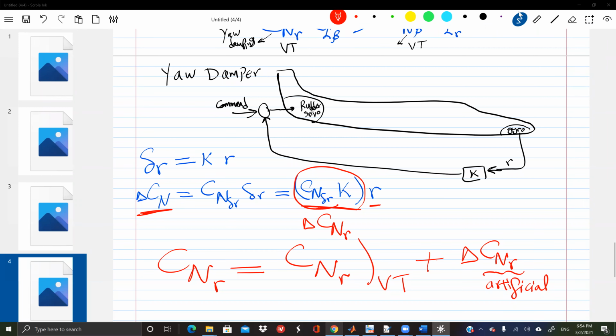So far, so good. Could I ask, are you basically just increasing the rudder angle a little bit with your gain constant? This will be continuously happening during flight, and the rudder angle will depend on R. There is a rudder angle for trim if needed, though usually there is none. There is a rudder angle coming from the pilot command. I'm not talking about that. I'm talking about the additional rudder angle for feedback control. This is proportional to R, the yaw rate of the airplane. So if the airplane is not doing any yaw, there's going to be no rudder deflection coming from this control law. It will only be activated whenever your sensor senses some non-trivial R. Okay, that makes sense. Thank you.